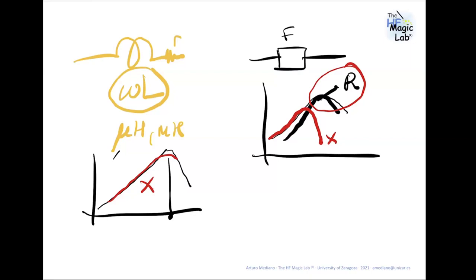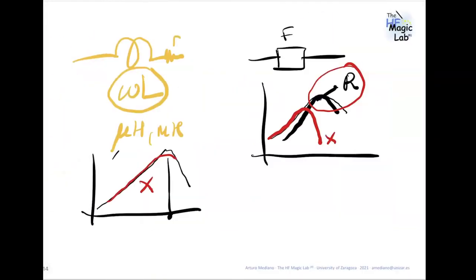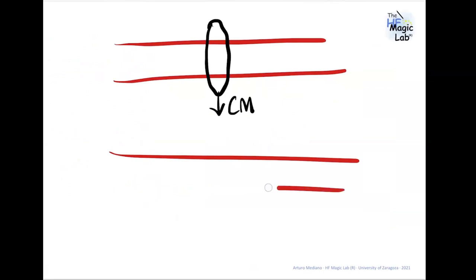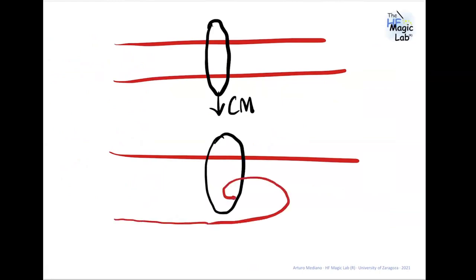Great. And sorry, but I think this is going to have to be the last question. Is it possible to characterize common mode and differential mode noise with a current probe? Yes, you can do that. It's the same idea as previously: if you have two wires and you want to measure the common mode, you do this, so you will get common mode. And for the differential mode, you do this. Let me draw here. You take the current probe, you put it in this area, and then the element goes in this direction. So the output of this current probe is 2 times DM.